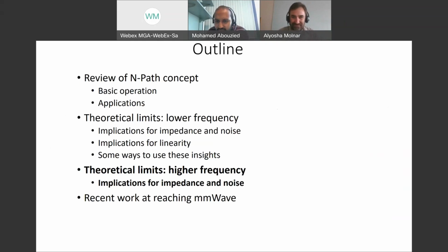Thanks for the presentation. Sometimes people use an inductive load at the LNA output side or mixer input. Does it mean the transfer function becomes RLC and gets better selectivity? So what you find is if you put the appropriate inductive load at the input of the mixer, it gives you an additional layer of selectivity. What usually is true is that if the mixer's baseband is reasonably narrow band, it will dominate. So in band, you'll have a narrow band bandwidth set by your mixer, and then you go out flat for a while, and then at some point the roll off from the LC resonance kicks in, and your impedance drops even further.